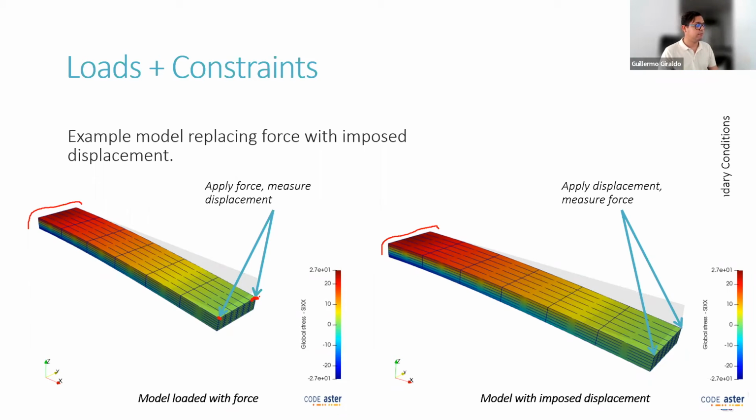If the parts are not initially in contact and you apply a force, then the displacement is not constrained because the physical contact is not active. Then what you get is a force on a rigid body motion, right? So the displacement is infinite because the physical contact is not active. So apparently you will get a divergence on your solver, and apparently there is no solution to this.